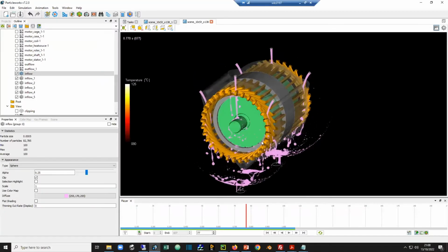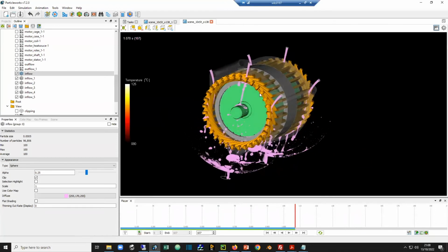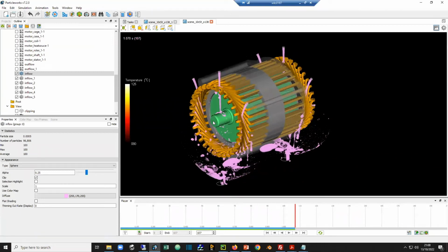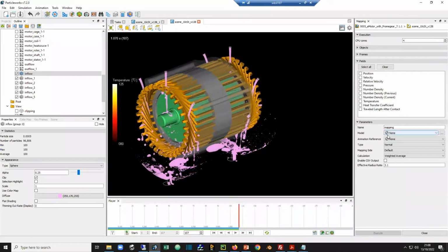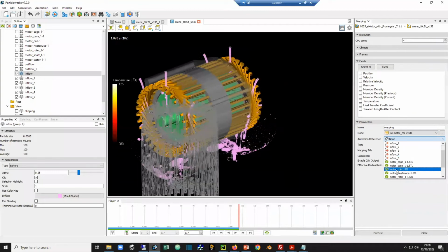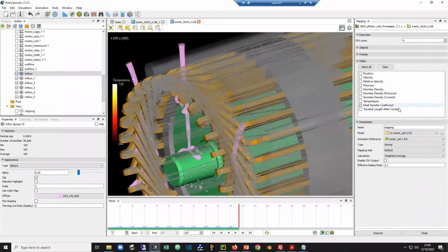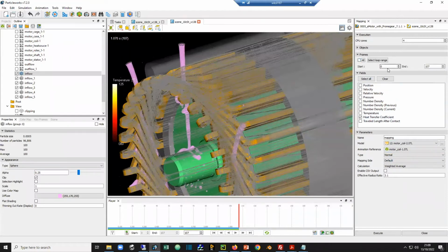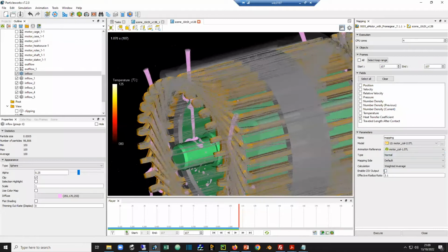Okay, what I would do then here, let's say I saw that the stabilization, so the number of particles is not increasing anymore, meaning that the oil that accumulates has stabilized. Once I get there, I could run some post-processing. One is the mapping post-processing that will actually project the HTC of oil onto a specific element, like perhaps the coils. So I can import the coils, that is the STL of the coils. I can do a map of the HTC, heat transfer coefficient, on the coils. I could do it maybe for a specific frame, or do an average, whatever. I could have a CSV output.